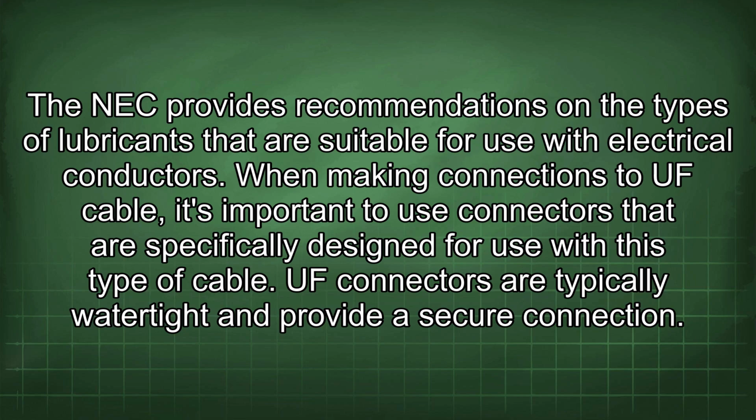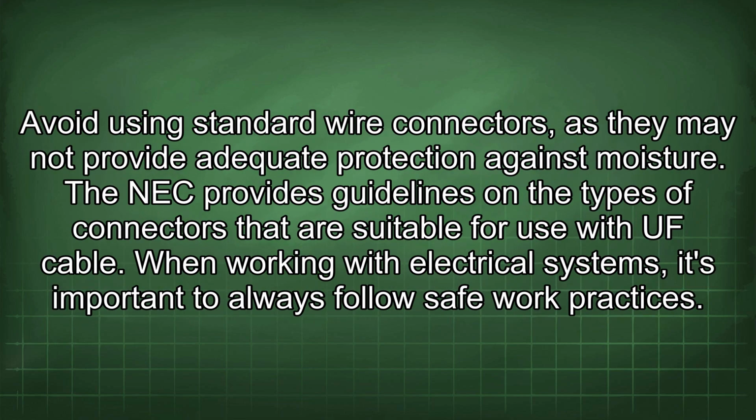When making connections to UF cable, it's important to use connectors that are specifically designed for use with this type of cable. UF connectors are typically watertight and provide a secure connection. Avoid using standard wire connectors, as they may not provide adequate protection against moisture. The NEC provides guidelines on the types of connectors that are suitable for use with UF cable.